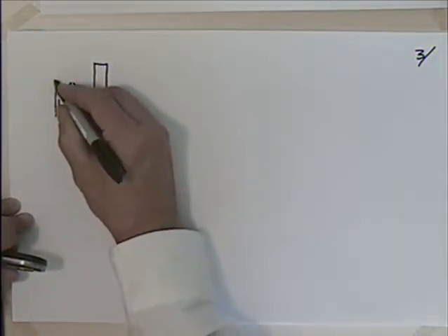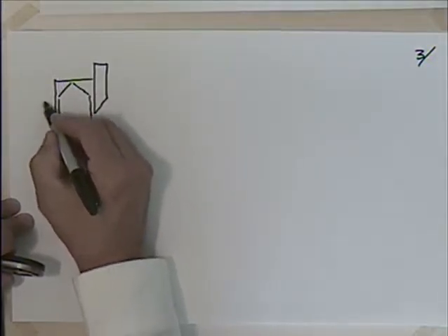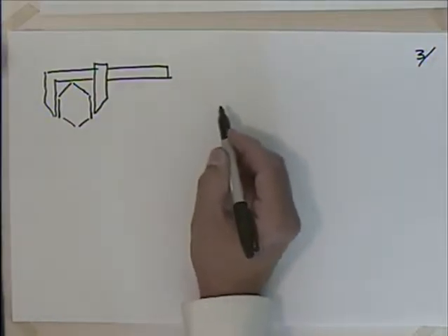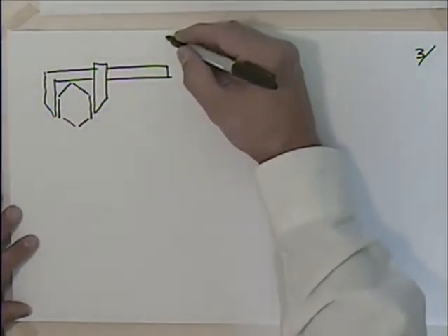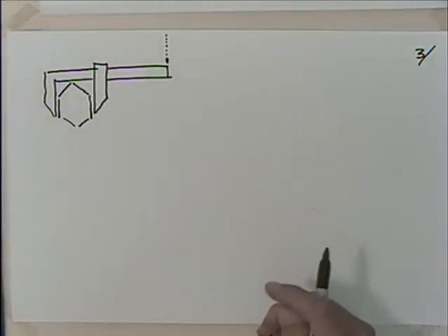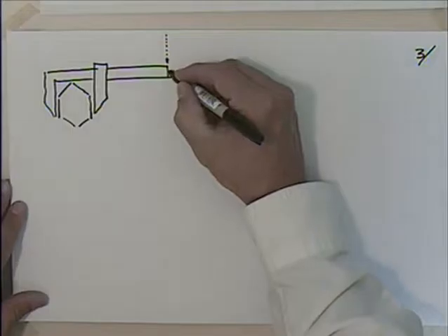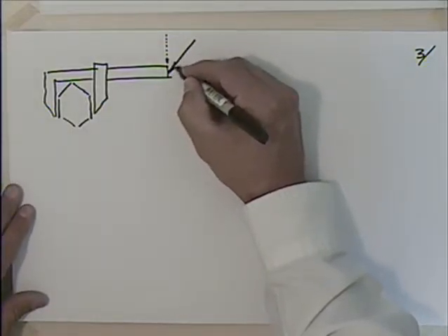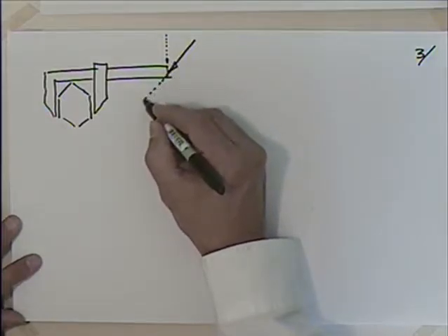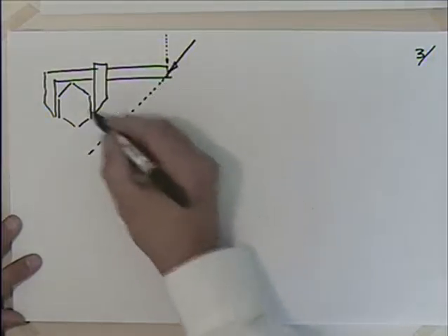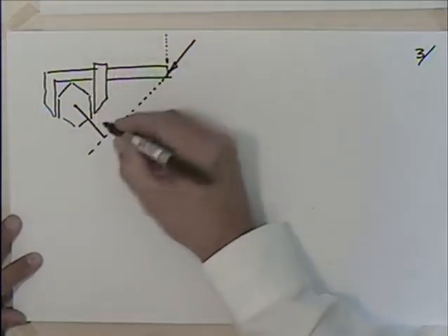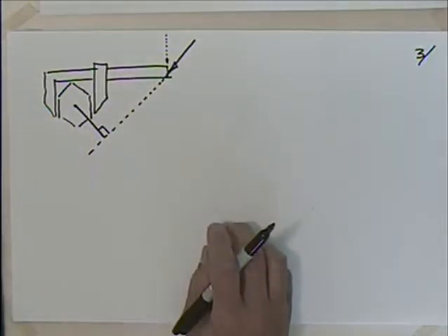So we'll draw our monkey wrench here, like this. And I drew the force like this, didn't I? You might say, well, good luck getting that in there. Sometimes you have to apply the force at an angle. That's fine. You can then look at the line of action here. And if you happen to be looking for the moment about this point, then you need to find this perpendicular distance right there, don't you?